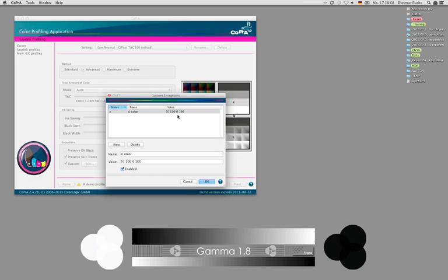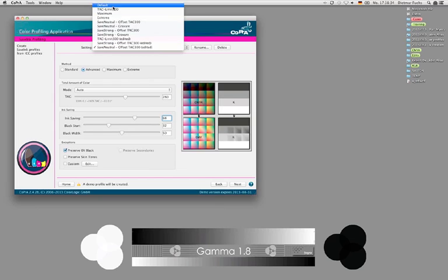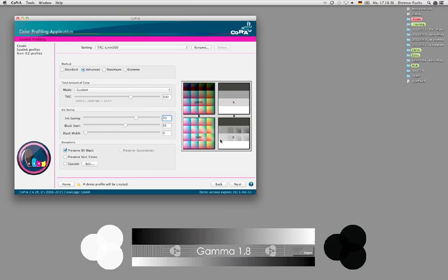So you can keep this color exactly as the client wants, if that is a specific color that the client wants not to be touched from the Save Ink conversion. And here in this graph, we always show as well which kind of settings it has. For example, if you use the Preserve 0% black, we don't add black in this area, which is used from our tag setting. For example, if I switch back to the tag limit setting, you'll see that this is not used.